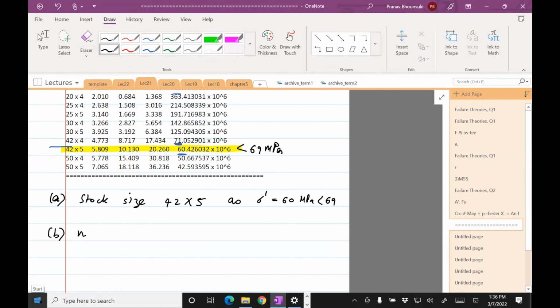So remember, the factor of safety is computed after the design is complete, right? So we've completed our design, and the factor of safety is the max stress, in this case, the yield strength, divided by the maximum stress. So SY is 276.